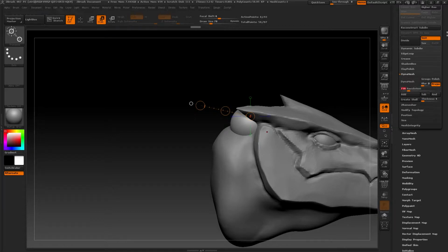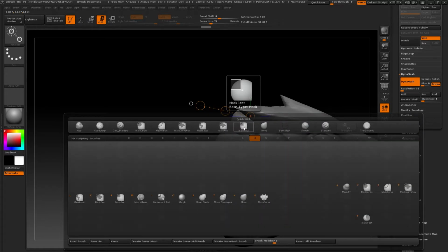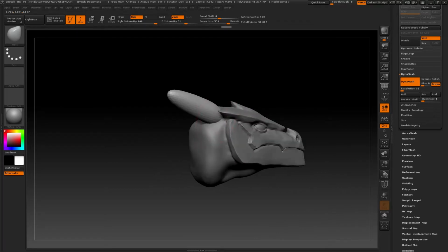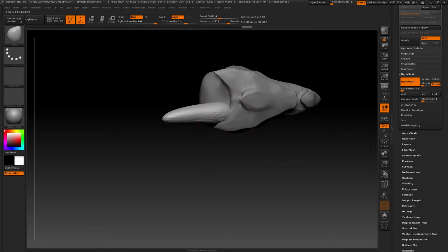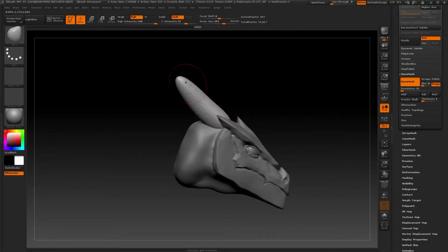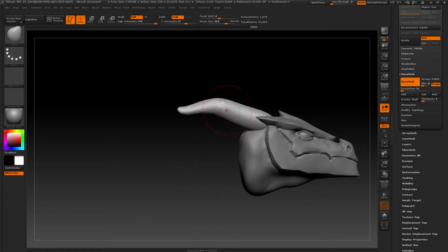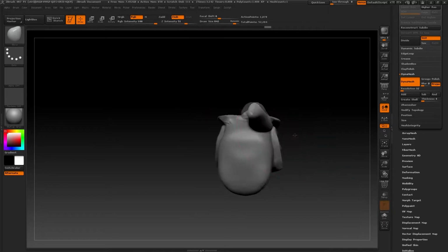Now, to carry on with the horn, activate the Dynamesh, as we're looking to generate different volumes to those of the sphere. We can move our model with the move. If you see that the model isn't working because the polygons are stretched, simply use Dynamesh. To do that, make a mask in an empty area that doesn't touch our subtool and carry on stretching and applying Dynamesh until you get what you want. I find this part the most fun. Just try out different things.